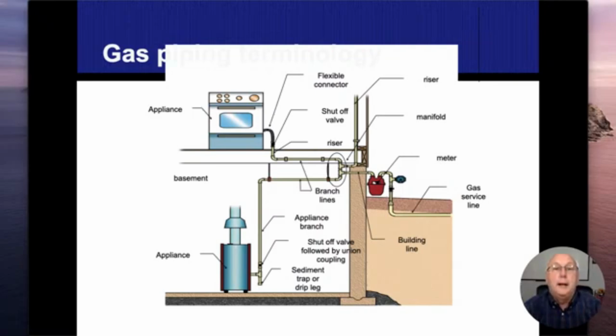But he was explaining to me that they do have some issues where moisture and water gets in there, and you have to have that drip leg because sometimes the gas valves got stuck in the open position and they couldn't shut down because of rust and corrosion that was there. That made a lot of sense to me, and it put a lot more importance on having a drip leg in there. All right. But mostly it's just to catch the garbage.